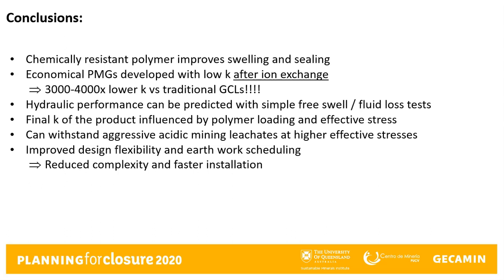The product can perform well against aggressive leachates even after ion exchange, and higher polymer loadings give improved chemical resistance. Higher effective stress results in lower hydraulic conductivities, and the new product should allow engineers to design more cost-effective installations that have greater installation flexibility.